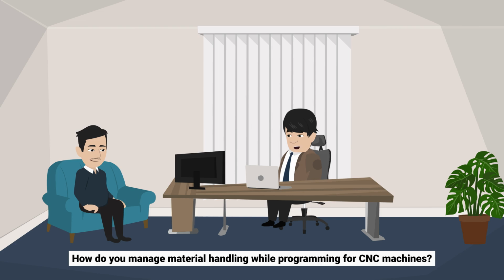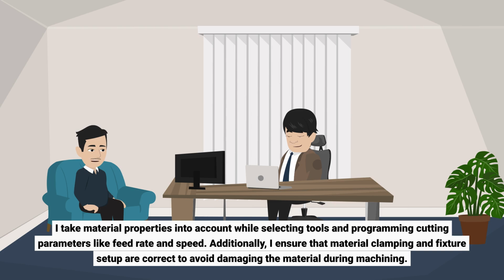How do you manage material handling while programming for CNC machines? I take material properties into account while selecting tools and programming cutting parameters like feed rate and speed. Additionally, I ensure that material clamping and fixture setup are correct to avoid damaging the material during machining.